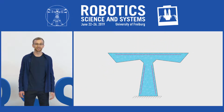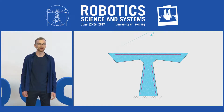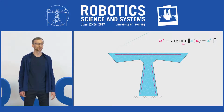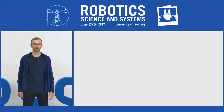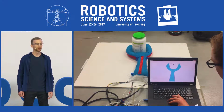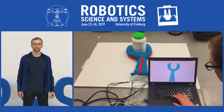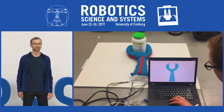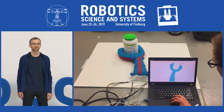Now, to do quasi-static control, we can specify a target position for the mesh x prime and optimize for corresponding control signals. This method forms the backbone of a system that we proposed a couple years ago called soft-IK, where a user poses a soft robot in real time by dragging around target positions for the nodes in a simulation mesh. Here, this is used to do a grasping task.